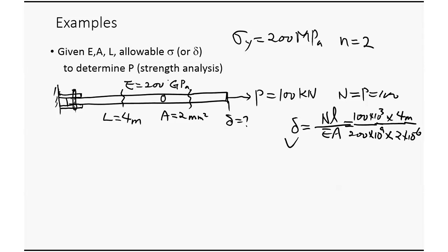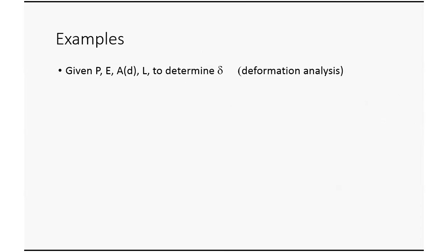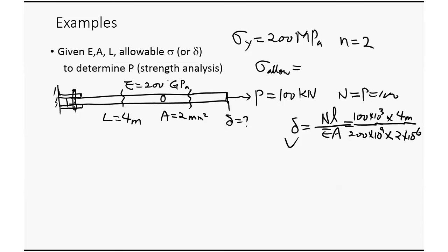Find out the stress. See if it compares to the allowable stress. If it's below, it's safe. If it's over, it's not safe, right? So what's the allowable stress? It's supposed to be sigma y over n.